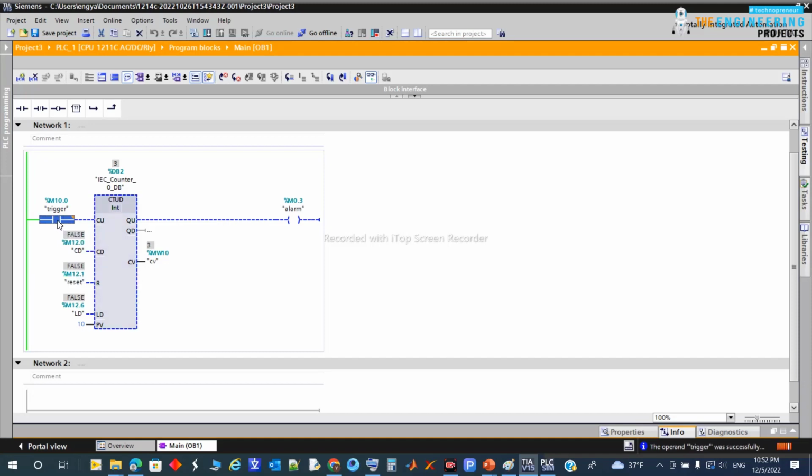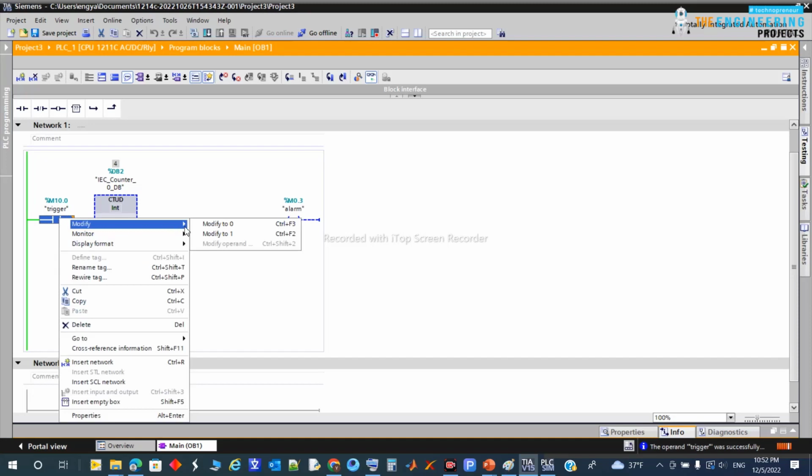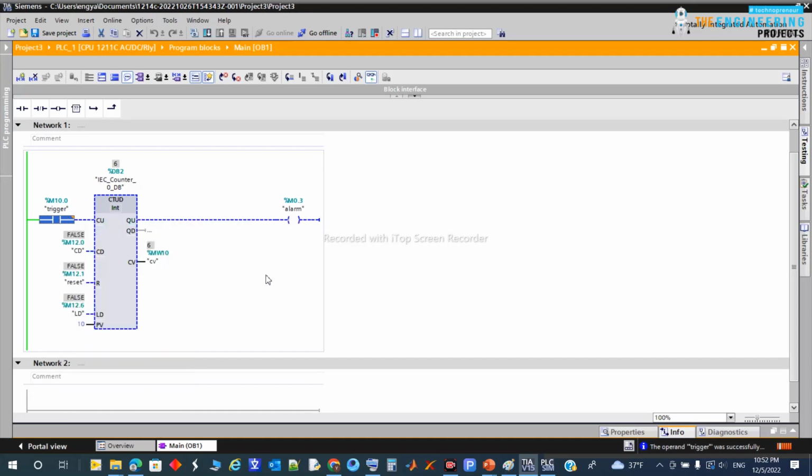This is 1, 2, 3, 4. I'm now giving pulses from here, forcing the trigger for this, and at any time I can reset. When I use this reset, see, it becomes 0 again. When I'm loading this one, loading makes the current value the PV value, the maximum, and then I can count down. So I can stop loading first and then count down like this.